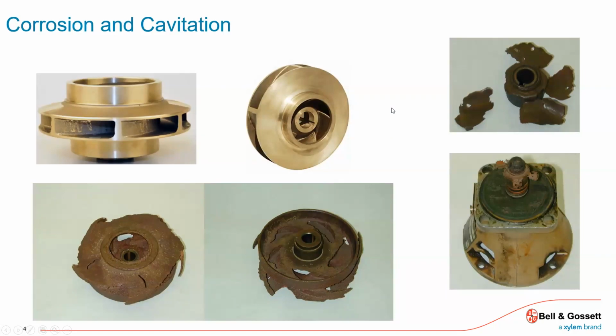I showed you, I think the first week, some actual impellers that we have in one of the shelves here. But air and an unusual amount of oxygen in a hydronic system will lead to corrosion and can also lead to cavitation, which will do a number on some of our pump components specifically.